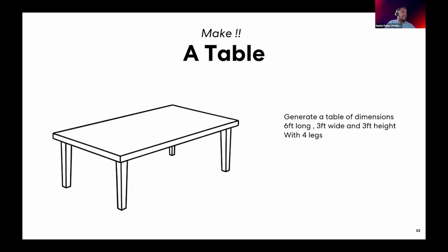This is interesting. I think this is the fascinating part of this workshop. You can see we are all trying to make a table of the same dimensions, but everyone's getting completely different results and errors. We'll talk about errors. By the way, if you get an error, you can just copy paste that error into GPT and ask it to fix things. In the first iteration, it gave me some code with, I think, ASCII characters or something that Rhino didn't like, and I got that error message. So I just copied and pasted that back into GPT, and it'll fix it for you sometimes, many times, hopefully.